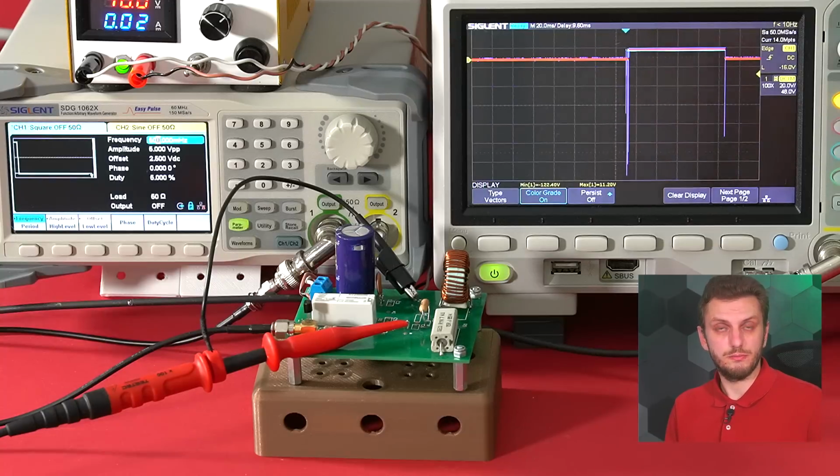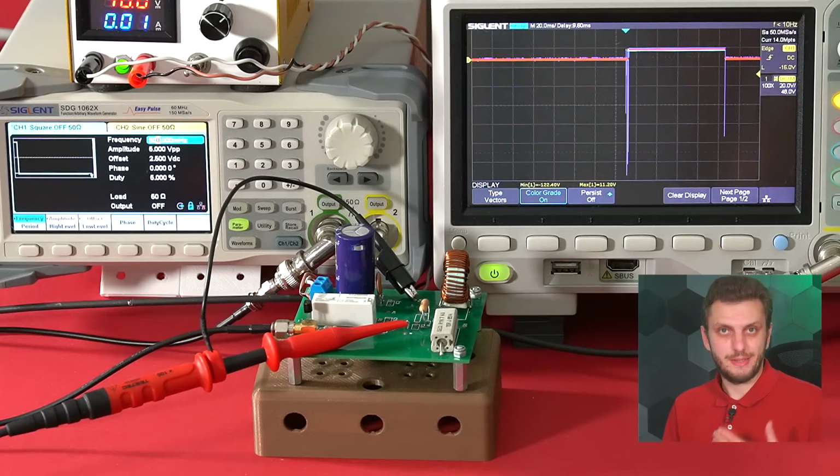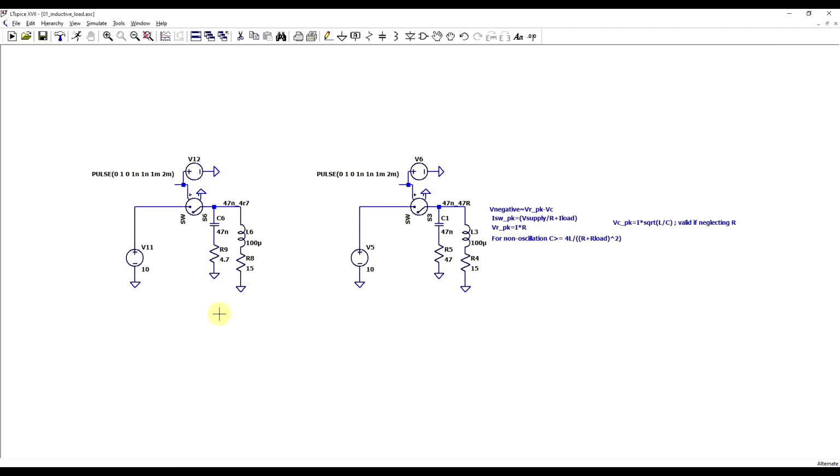To make sure that your circuit runs reliably, you need to choose the right type of component. Now, by going with resistor-capacitor networks, we kind of fixed both issues. There is no permanent DC load, since DC current cannot pass through the capacitor, and at the same time we can use smaller resistors, which will ensure smaller reverse voltages. And with smaller voltages, we will get smaller peak power levels.